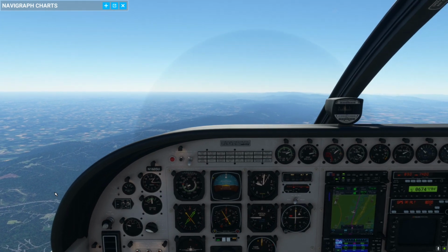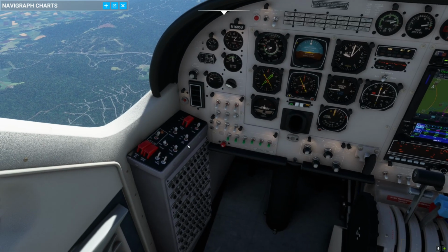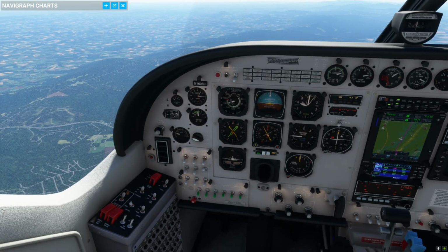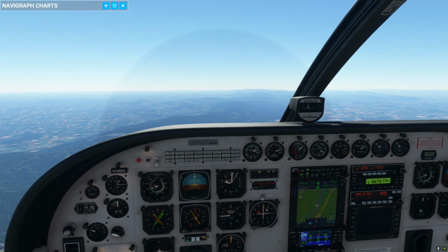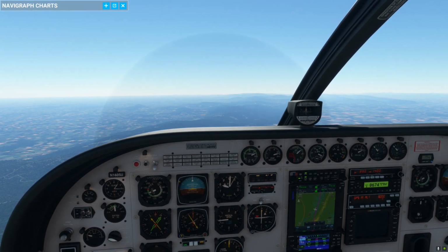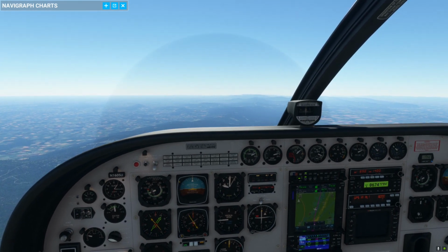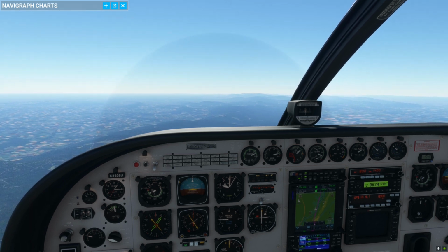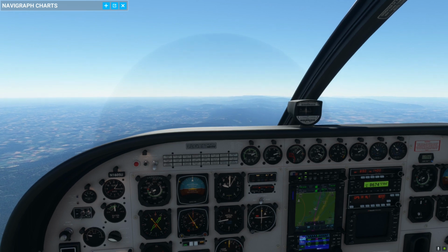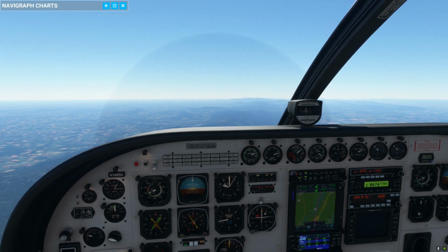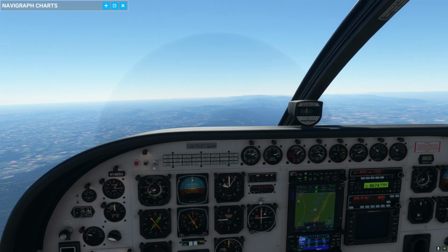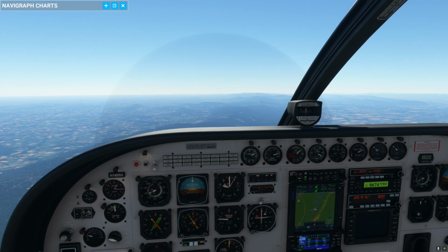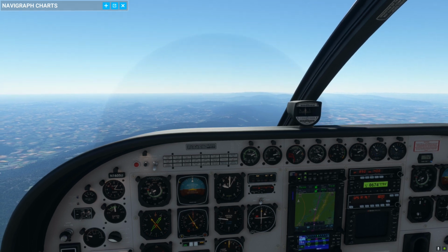All gravity fed. It does. There is a, well, obviously not totally because it has a fuel pump. But honestly, the engines would run on full gravity feed. If that fuel pump died, wouldn't be a big deal. If you're in a low wing aircraft and the fuel pump dies, yeah, you're probably not getting any fuel to the engine. That's why you have multiple tanks and crossovers. When we get to multi-engines, well, I hope we don't have to play with all that, but you'll be able to see it.